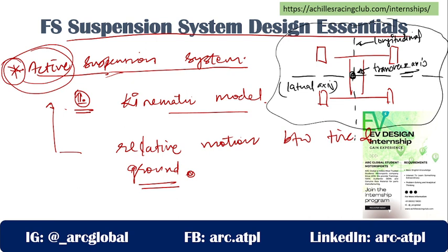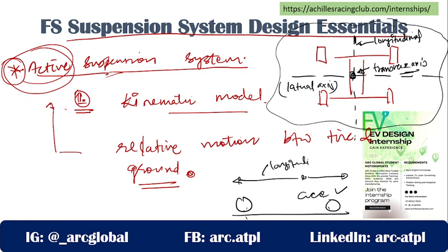This is how we do it for the ease of our calculation, for having certain references to solve the numerical statements. The forces that are acting along the longitudinal direction are divided into longitudinal forces. These forces you will find as the traction forces. The forces acting between the tire and the ground in the front to rear or rear to front direction are regarded as the longitudinal forces. What are these forces? Acceleration forces, right? And the deceleration forces, right? Altogether, I can say the longitudinal tractional forces.